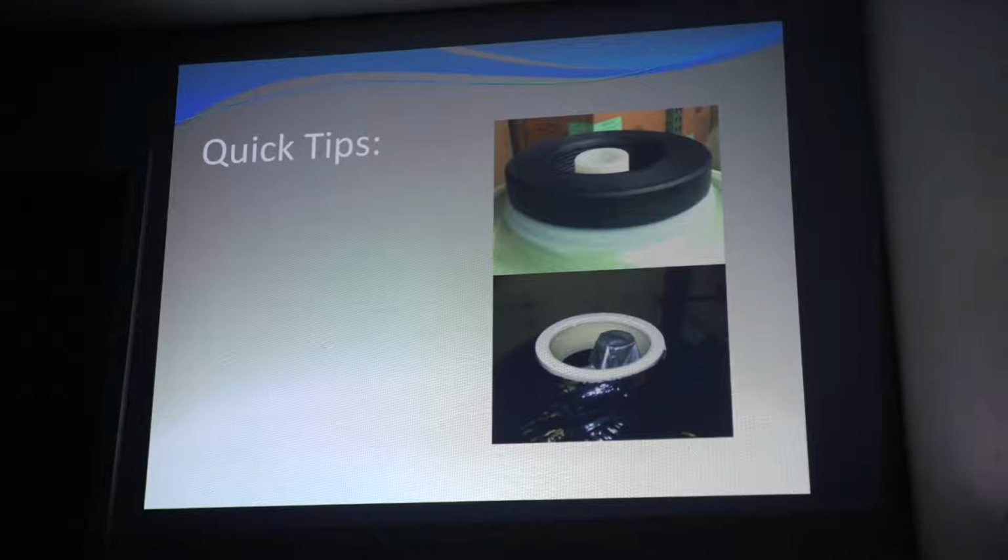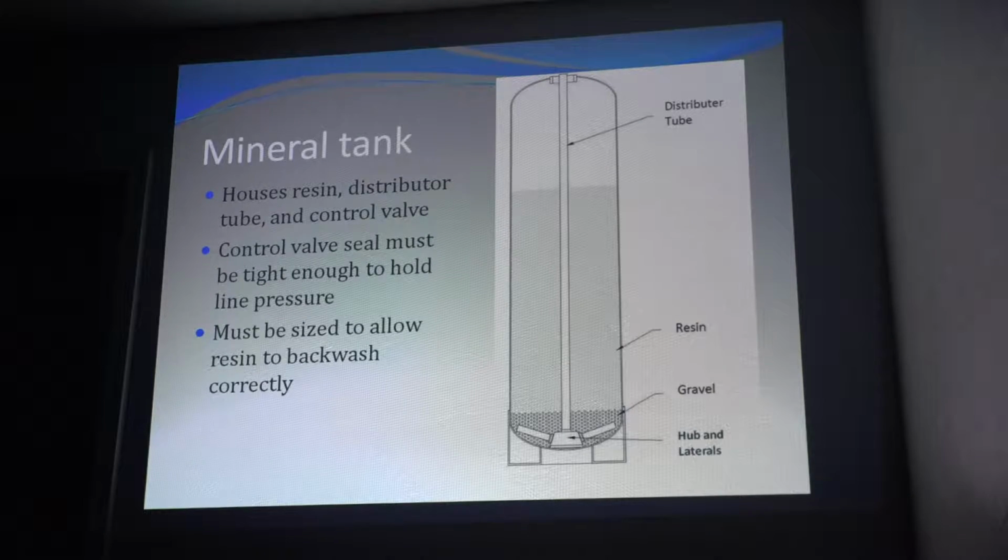People will see that we have an empty spot above the resin, the open air, and say, well, why don't you just fill it right tight with resin? The water softeners that we build are designed to have 50% freeboard space. We need to lift the resin 50% during the backwash cycle.